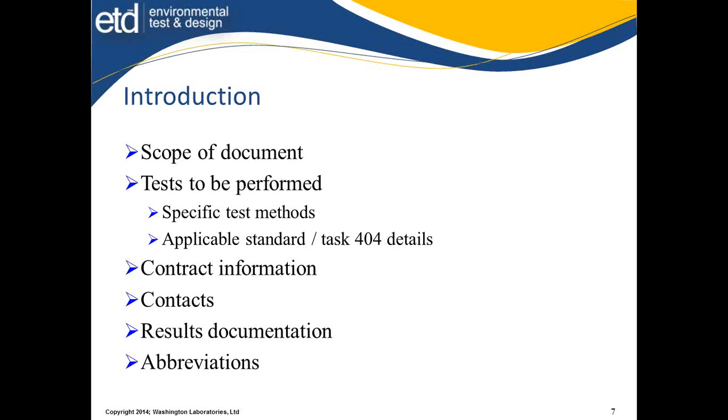Which tests? Am I going to do everything according to Mil Standard 810? Or am I going to integrate things from my IEC 60068 or DO-160 or various other environmental test standards for specific applications?